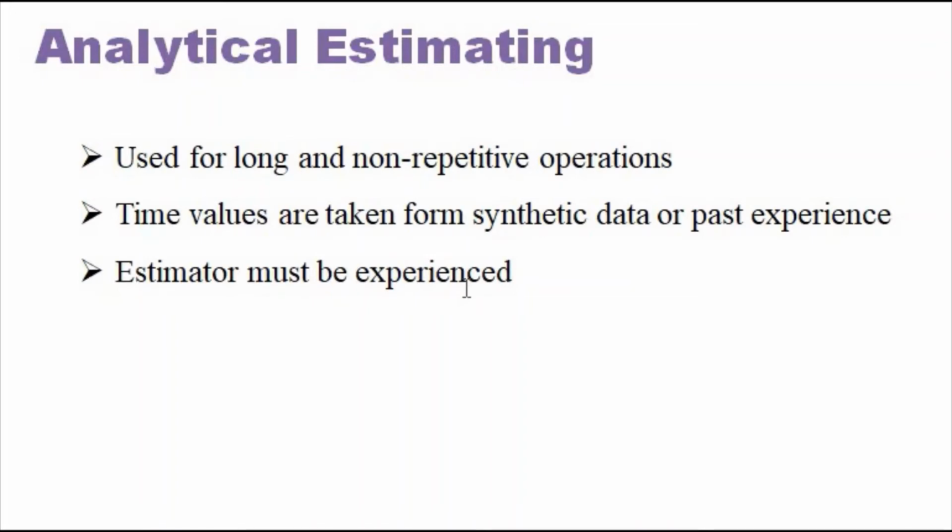But in that case, the estimator must have sufficient experience of estimating, motion study, time study, or synthesizing the time standards. If he is good with that, then the past experience of the estimator is also used for analytical estimating. But if sometimes a standard data or a synthesized data is available, then that data is used. Generally, it is followed for long and non-repetitive operations.